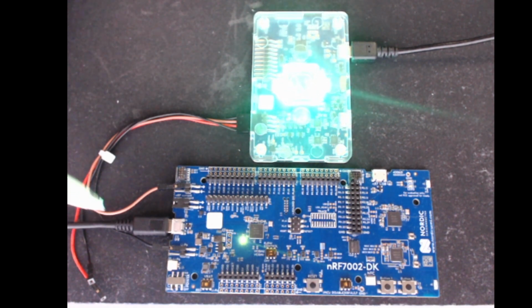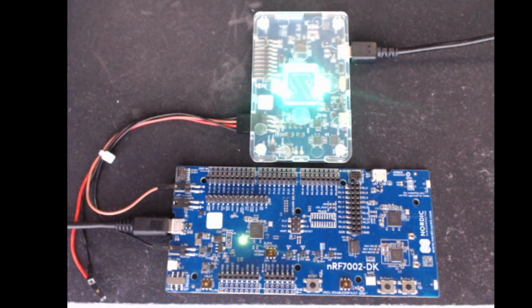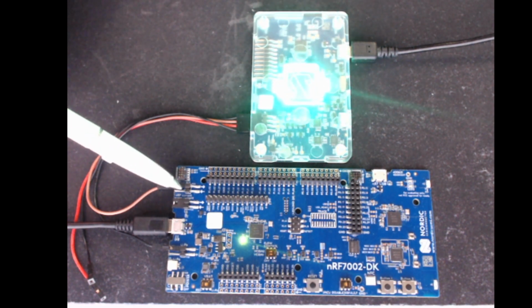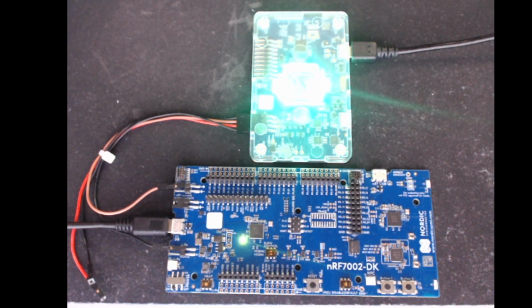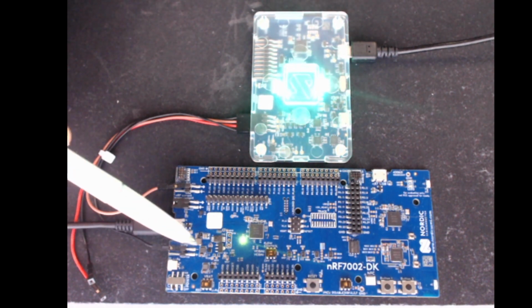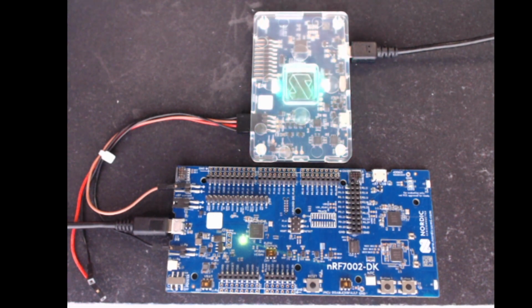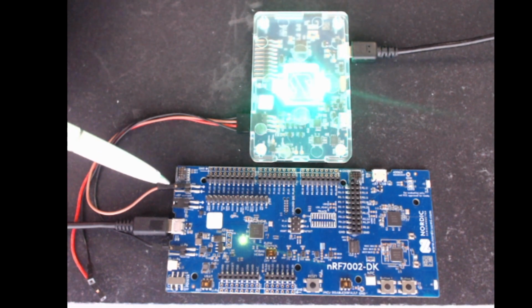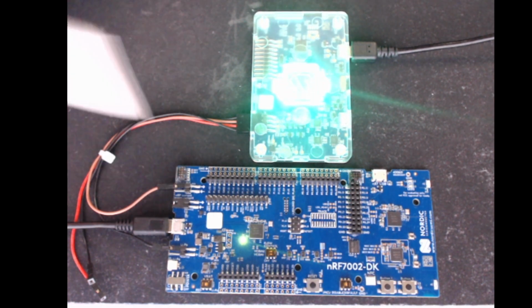And this connection here is simply following the documentation for the nRF70 Series. So there is a section for power profiling. What it instructs us to do is to remove the jumper on connector P23, which is the one here at the top. And then we need to connect the PPK2 to ground on the board. So we're going to be using pin 1 on P21 down here, so the one with the minus label. And then we're going to connect Vout, which is this brown wire, from the PPK2 into pin 1 of P23, where we took out the jumper from.